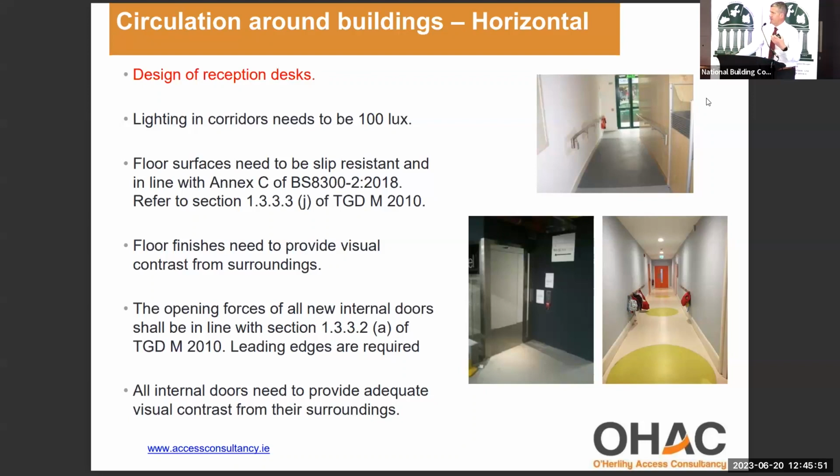They accommodate staff on the staff side and stuff like that. And 99 times out of 100, the hearing induction loop is never installed. And if it is installed, people don't know how to use it. Lighting in corridors needs to be 100 lux. And floor finishes need to provide good visual contrast from their surroundings.